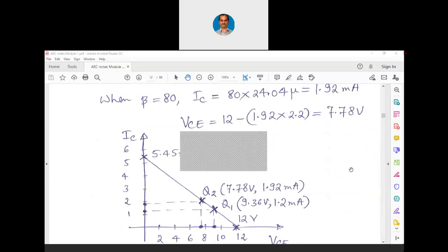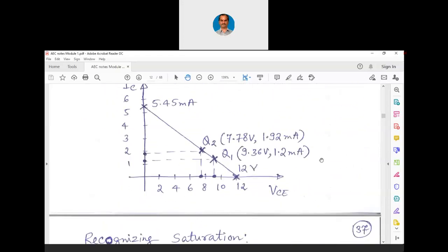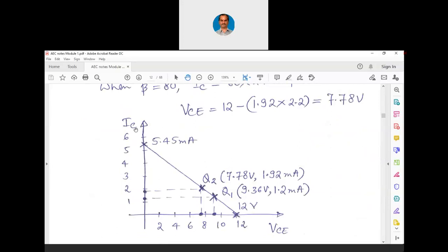Let me show you this particular curve. Using the same results, I have plotted this particular curve. Okay. What is that question? What is IC saturated? IC saturated means when the transistor is completely on, the current which is flowing through the transistor, that itself is called IC sat. What is 0.7? That means Nirmit was absent yesterday. 0.7 is the base to emitter voltage. Refer to the previous class videos.